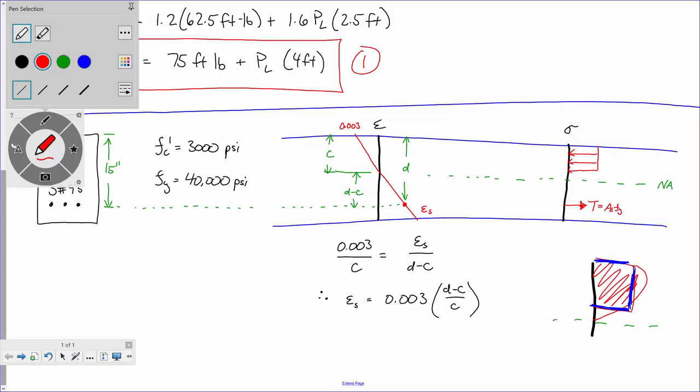Okay? And what is the width of that stress block? It's not f'c, it's how much f'c? 0.85. And that is always true. Remember, that's our empirical relationship that relates this nonlinear area. That's the relationship that'll give us an equivalent moment.